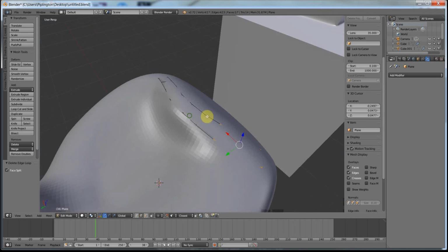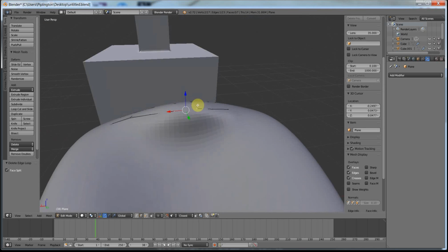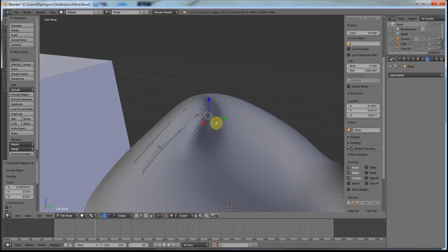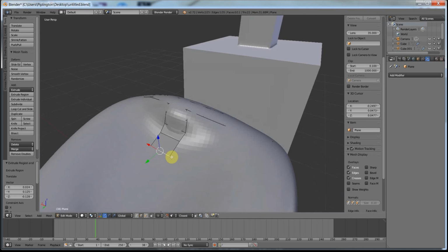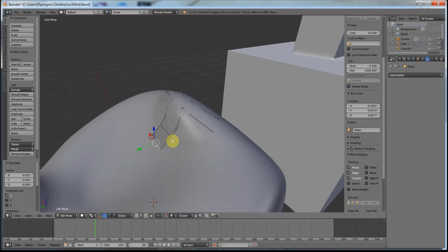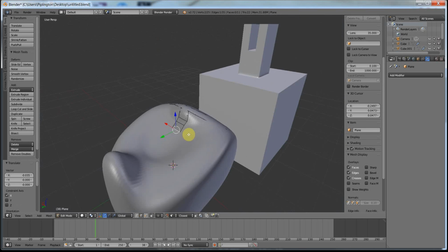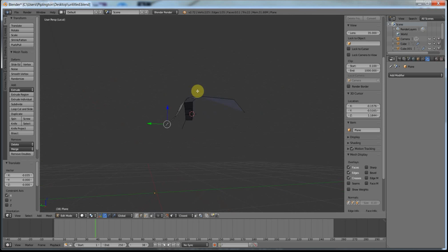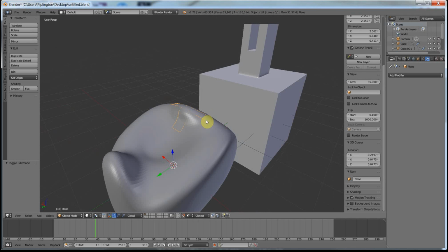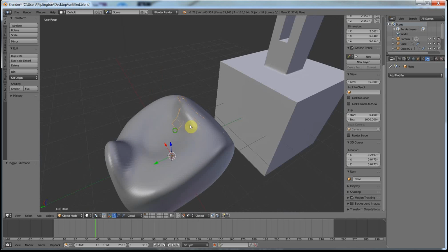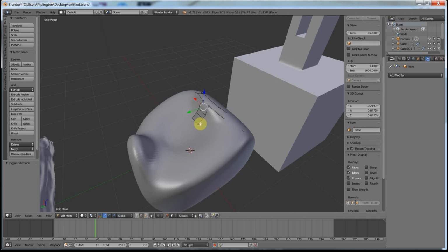But now that I've done that, I can also extrude down here, start creating this shape. So I'm really just putting in some random edge loops, not very precise. But when I isolate the object with backslash, we can see that it's starting to build the same shape, but with less polys. So we're starting to build the low poly asset. And then I could continue on like this.